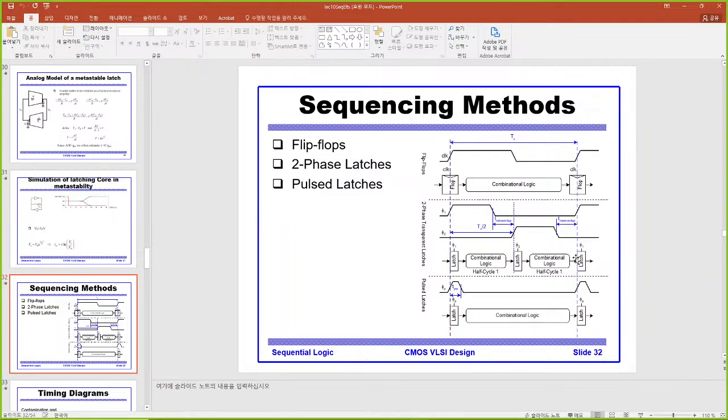To take into account such time borrowing, the CAD tool is not efficient or accurate enough to consider all the different cases, because you have to know all the timing information nearby the logic, logic delay, and also the clock phase information.